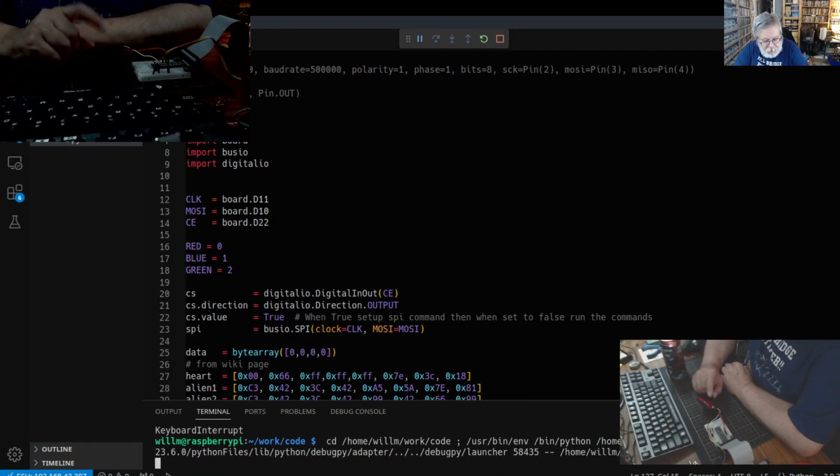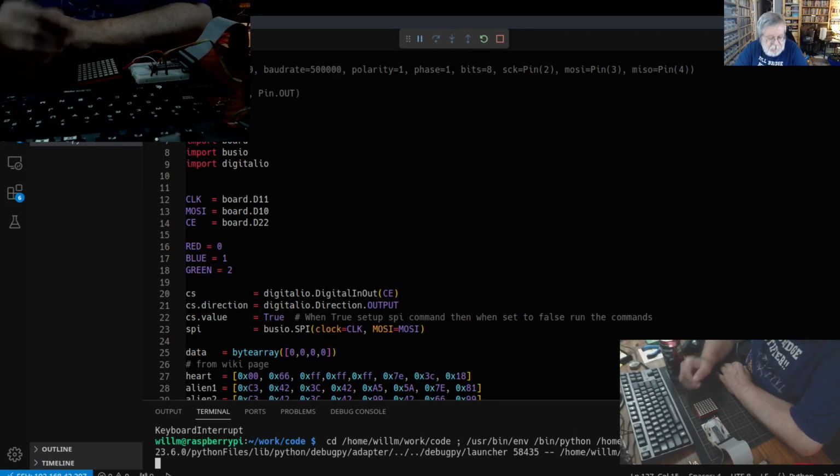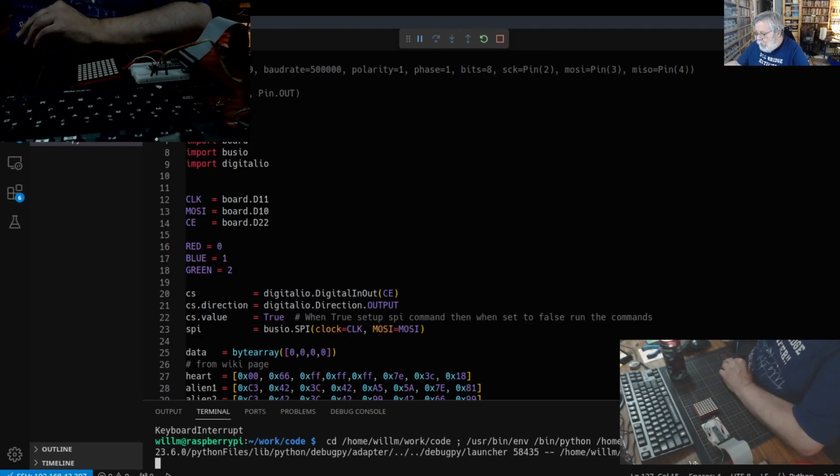We have what's known as shift registers on here. These 4 black chips. You can see them right there. Shift registers are otherwise known as Texas Instruments 74HC595s. If you check the data sheet out for them, which is one of the first things I did, because Raspberry Pis, unlike the microcontrollers, do not handle 5-volt controls from a 3.3 volt pin. They don't like it.